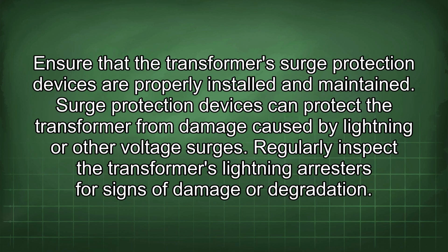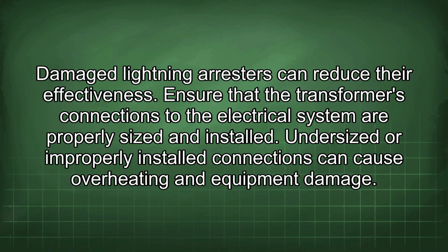Ensure that the transformer surge protection devices are properly installed and maintained. Surge protection devices can protect the transformer from damage caused by lightning or other voltage surges. Regularly inspect the transformer's lightning arresters for signs of damage or degradation. Damaged lightning arresters can reduce their effectiveness.